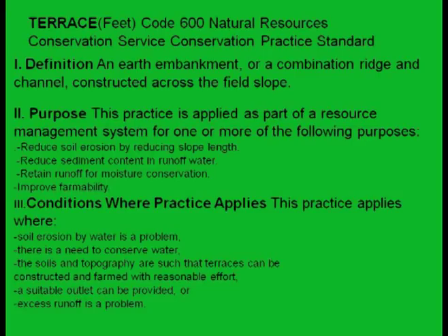We don't want to create systems that cause erosion going to the ridges. It's already causing erosion in valleys. Let's not cause more erosion. So that's why I dial in with the laser level, because I try to keep it within 1% either way. So I use 1% slope as my steepest grade when putting in swales. You can use hand tools, shovels and picks, and just observe this for a second.